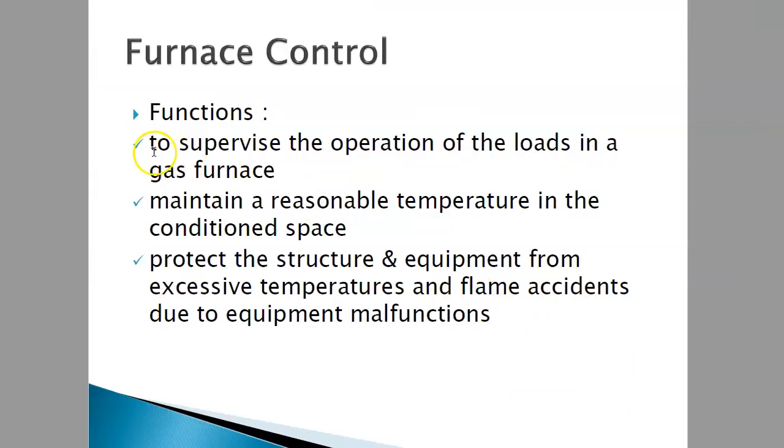Okay, furnace control. Its function is to supervise the operation of the loads in the gas furnace and maintain a reasonable temperature in the conditioned space. This is for the heating season, so heating in winter. Basically, it protects the structure and equipment from excessive temperature and flames due to equipment malfunctions.